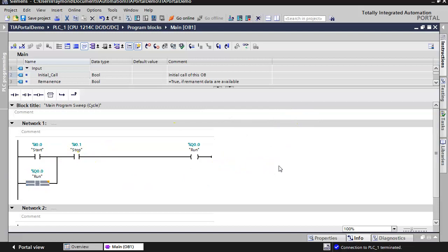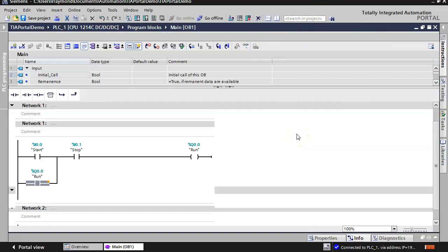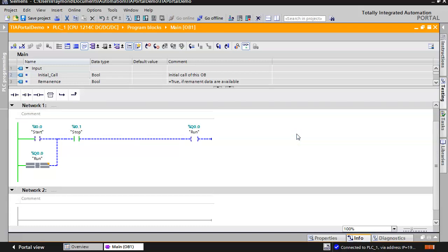Now on this one, it doesn't show you automatically like RSLogix 500. When you go online there, it already pops up and gives you the view mode, right? It shows what contacts are enabled and disabled. On this one, we have to click on these little glasses up here. And what I like about this is it shows you the entire flow. On RSLogix 500, all it does is turn the screen across contacts that are true. This one shows my stop is true because it's green, but my signal flow is stopping right there. So I'm going to come up here and click the start button, and it's sealed in and my light turned on at the front.